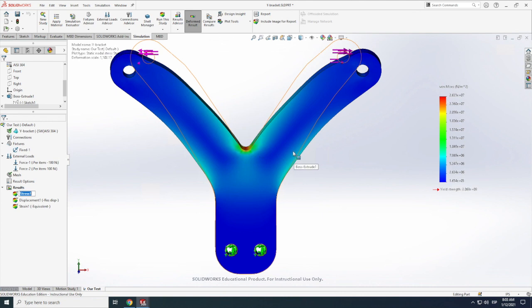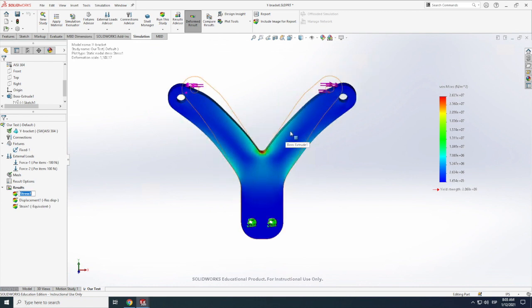All right, so now the simulation is done, and thankfully it did more or less what we expected to happen. Essentially, these orange lines that you can see denote the original contour of the shape. And this colored shape denotes the deformed version of the shape, even though this is of course very amplified. For the purposes of our visualization, we're just amplifying the actual deformation. But well, it did work. This moved right, that moved left, and we can see the stress in here.